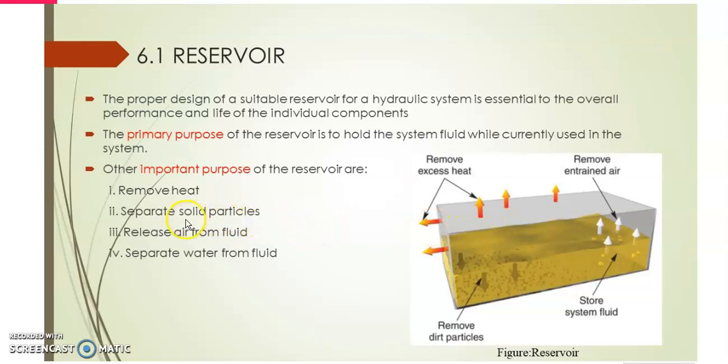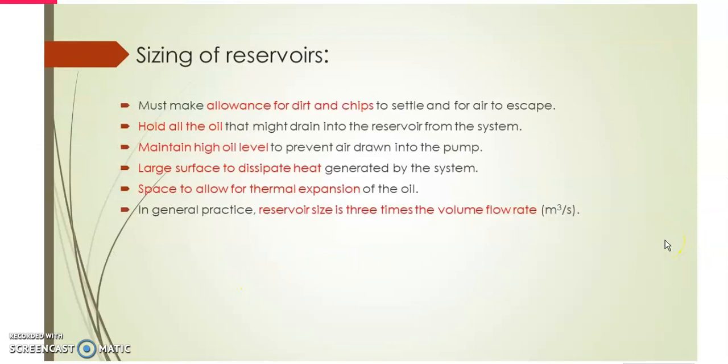The other purpose of the reservoir is to separate the solid particles, so we can remove the dirt particles, release air from the fluid, remove the entrained air, and also separate the water from the fluid. These are the purposes of the reservoir.